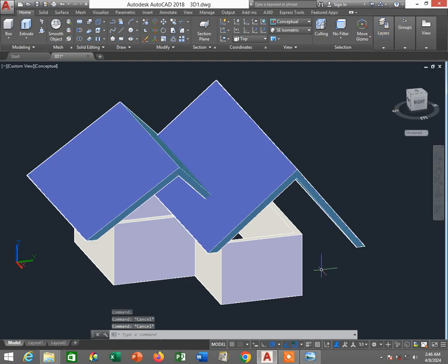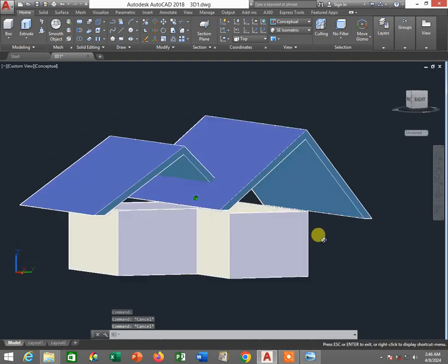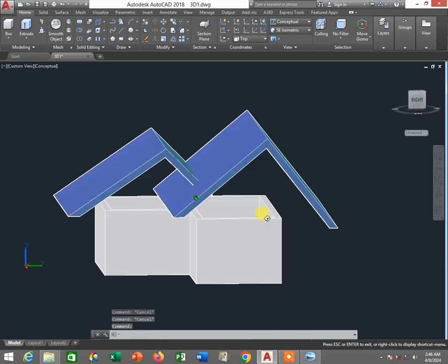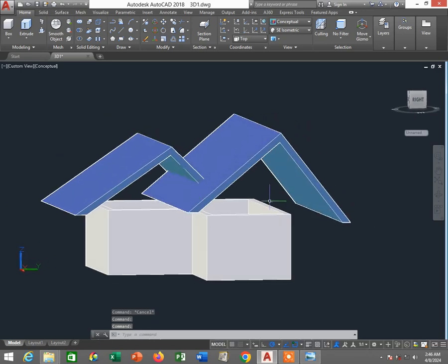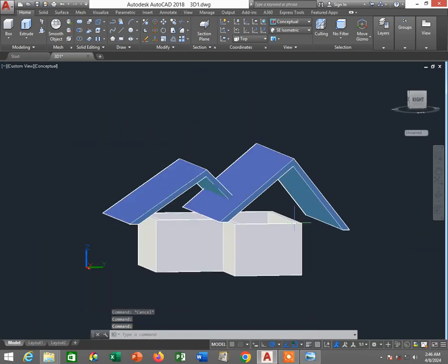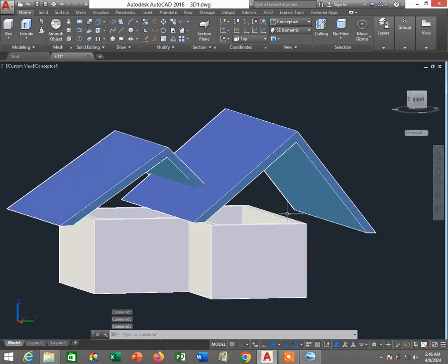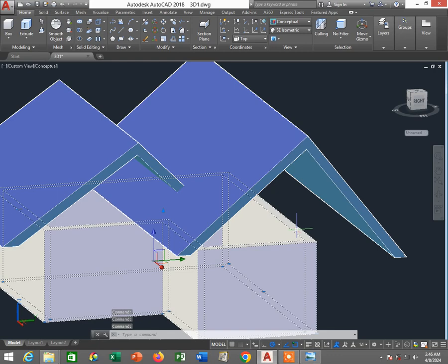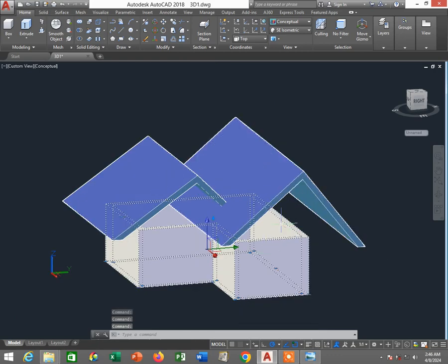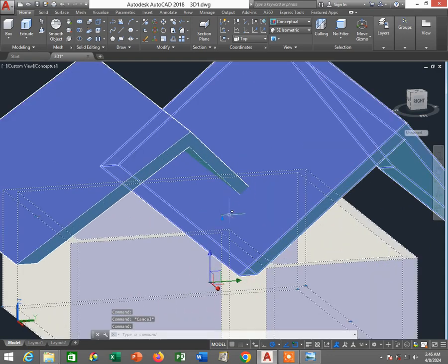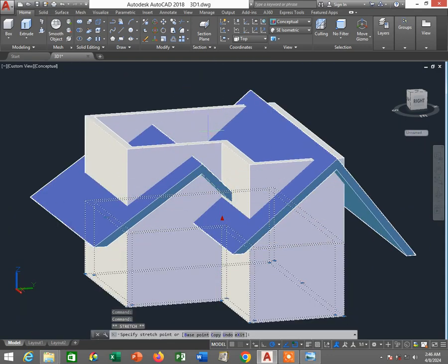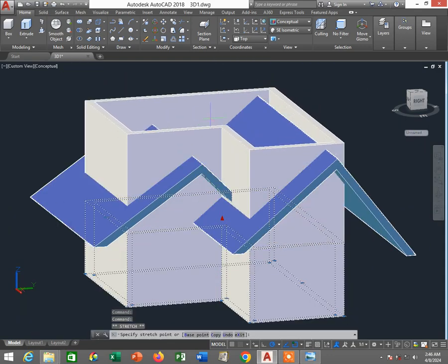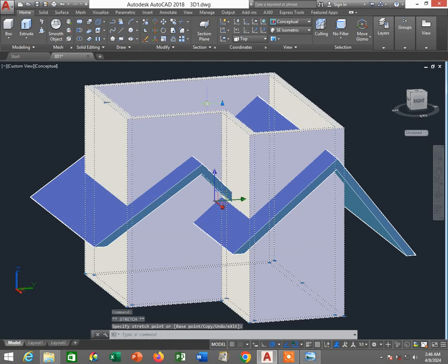Okay, and now I will try to increase this length. I want to actually extrude this wall so that it hits the top. So I can just select the wall like this, and click on the blue arrow over here, and I can just push it up a little bit by just clicking it.